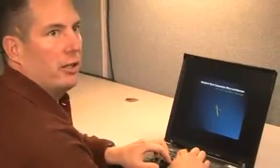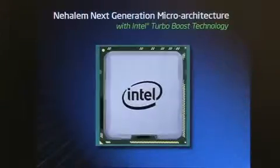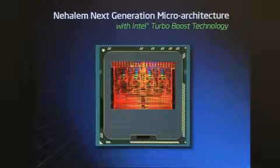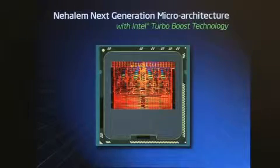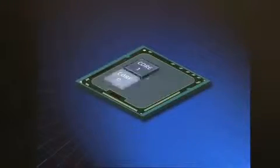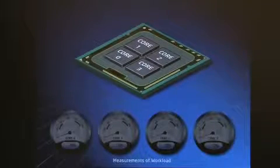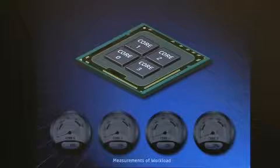What Intel Turbo Boost technology does is allow you to maximize the performance of the processor under a wide range of applications, under a wide range of usage conditions. What I'm zooming in on here is an actual picture of the die floor plan. On the first version of the Nehalem family of processors, there are 4 processor cores, so 4 independent processor cores, all able to run tasks independently of the other 3.